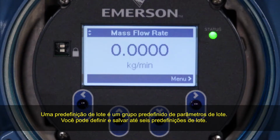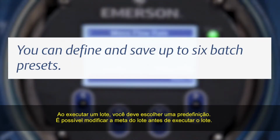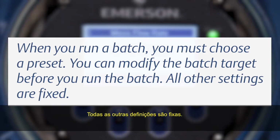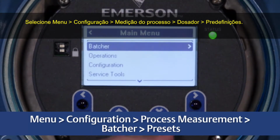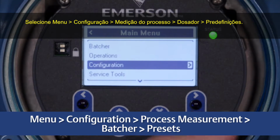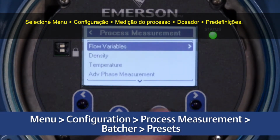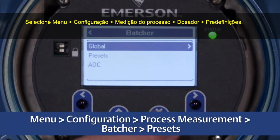A batch preset is a predefined group of batching parameters. You can define and save up to 6 batch presets. When you run a batch, you must choose a preset. You can modify the batch target before you run the batch. All other settings are fixed. Select Menu, Configuration, Process Measurement, Batcher, Presets.